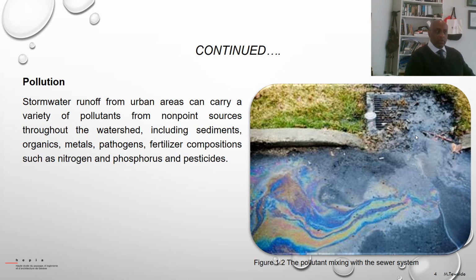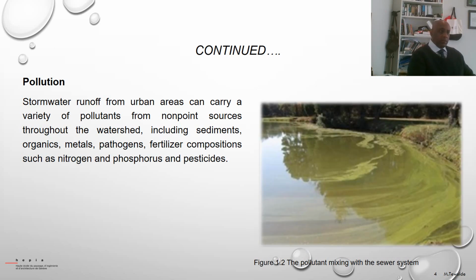And you can see as well the manhole is almost closed, half of it closed, and this might increase the temporary detention of water, and there will be temporary inundation around that area also. So manholes should be cleaned at least a minimum of one time in a year.